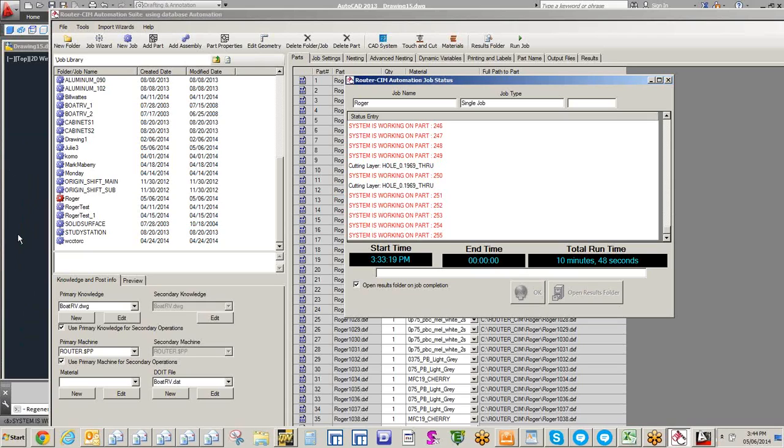One other thing that I think is really unique is that my customers started telling me how much tool life improvement they got. As you can imagine, all the plunging and in and outs is, I won't say harmful to the tools, but it definitely is creating heat, friction, and wearing out the carbide tools. So they're telling me that the number of sheets they're going through with the same tools goes up tremendously.